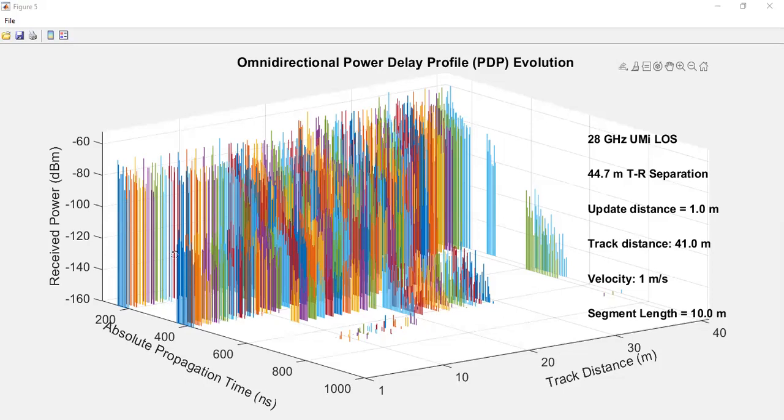You see the power level is a little lower, right? The maximum component is now around -80. For directional, it was around -50. So for directional, you are confining your power towards the receiver, whereas in omnidirectional you are spreading it in all different directions. Makes sense? Any questions?